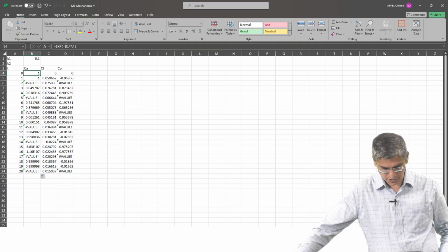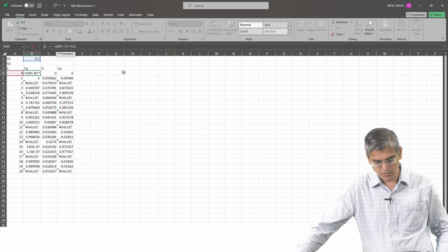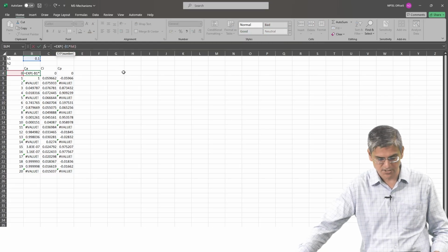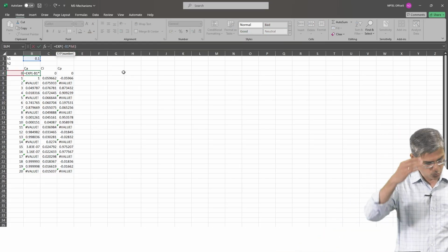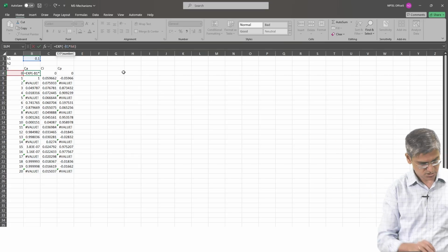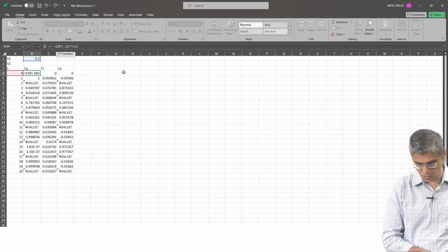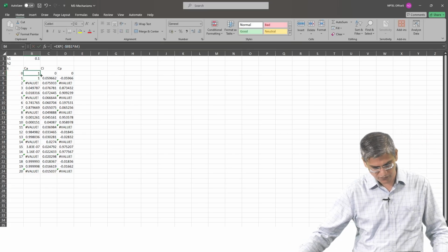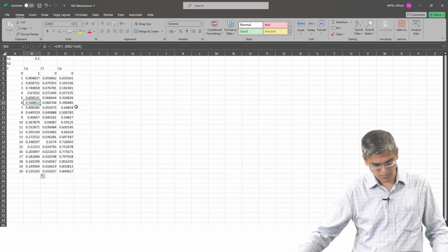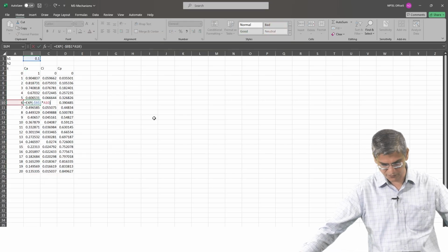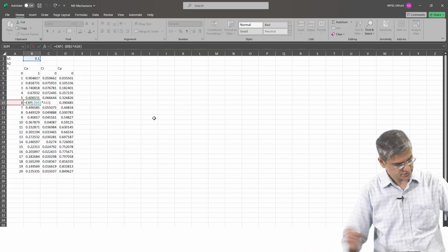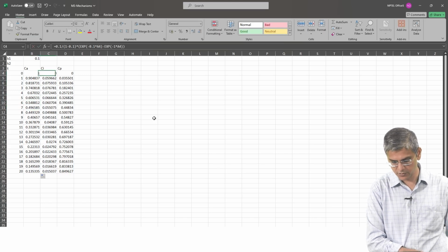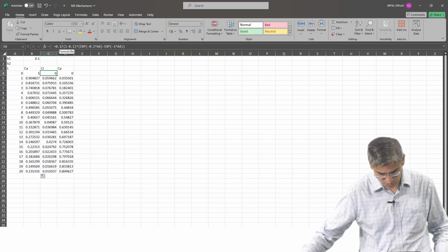So, what we will do over here is we will put dollar sign. The rows are 1, 2, 3, 4, 5, the columns are A, B, C, D, E. So, we do not want this to move down the row, we do not want to move this along the column. So, we will put dollar and dollar at both places. And now, if we drag and drop, this is what you are going to get as it was before, right. So, our K1 does not change its location. Same thing we will do over here wherever K1 is. So, this is where K1 is.